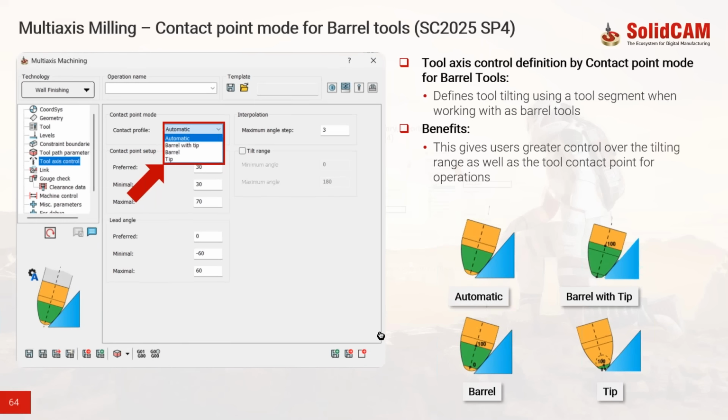As we have it also in the HSM, now we also can do it in rotary, geodesic, and multi-axis milling technologies. We can now define the boundaries by selecting the surface, pick up the surface, and the boundary will be created. Very easy, very nice and convenient.